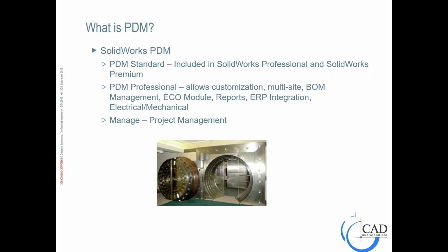The second thing that the PDM system does is it completely fixes the challenge of working on a client machine and a server machine. If you're using SOLIDWORKS in a multi-user environment and you want to store your folders on the network, you are typically working on that network drive, which is very, very inefficient. SOLIDWORKS is constantly reading and writing to the actual files. So you're reading and writing over your company's local network, which has a very small bandwidth when you compare that to the internal bus of your workstation.